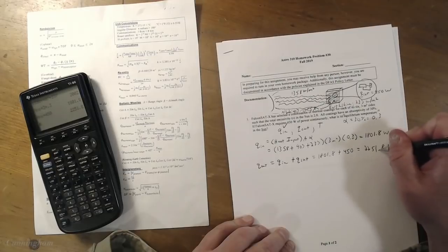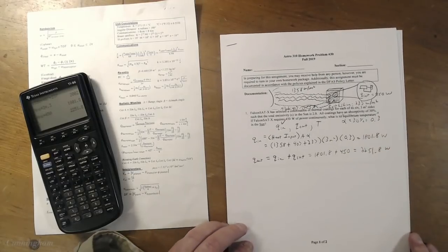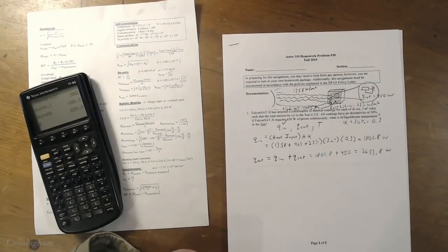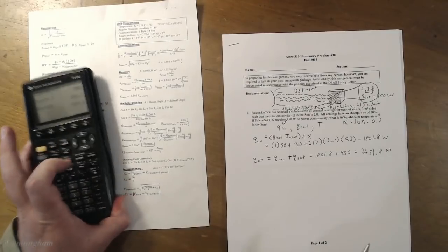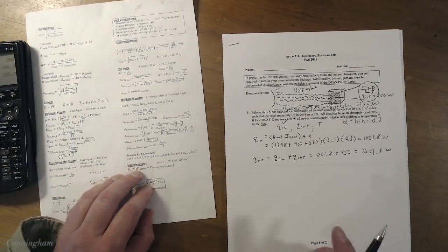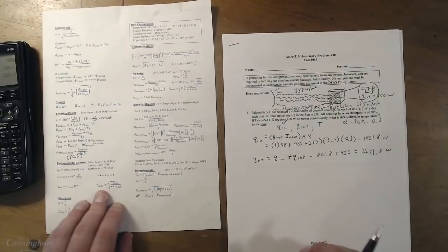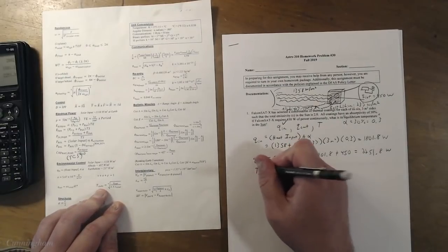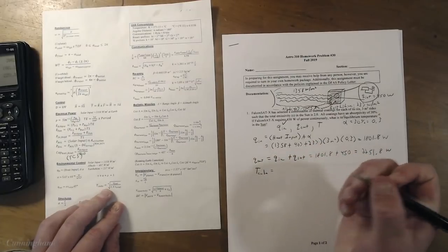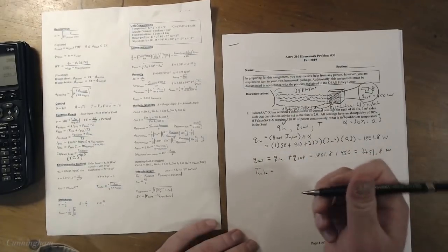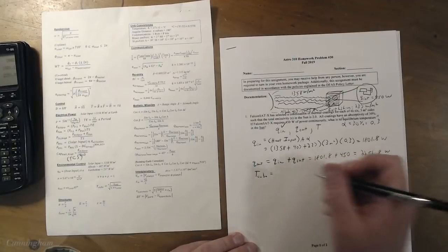2251.8 watts. So the amount of heat that FalconSat needs to get rid of to manage, if you will, is 2,251.8 watts. Okay. So what that means is we're going to use this T cube equation, which is written specifically for objects that are a perfect cube. And we're assuming FalconSat's a perfect cube.